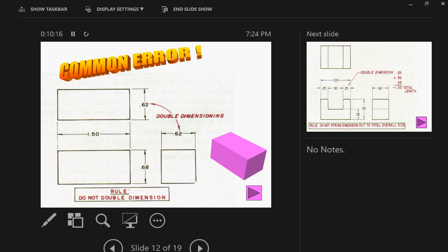Now notice you have 6 spaces, and then here it's saying, okay, from here to here the distance is this and this is the tolerance. And these all have to be so much distant, 0.25 or 0.5 apart. Now they've all got to stay within tolerance of each other. You're not going to have the same tolerance stack-up issue. So again, this goes to how much you want to control.